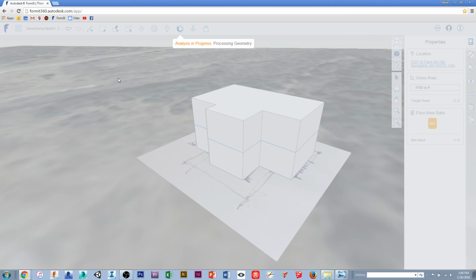And so as it's doing that, with this Insight analysis, we're going to see sort of this interface that I don't want to compare it to Pinterest because that's kind of silly, but that's kind of the notion. We've got all these little different boxes pinned into place on my Insight 360 that's built for this massing model. And each little window or each pin has specific data on it that's going to give me the opportunity to modify that data, like the type of HVAC system, how much glazing is on each surface, and immediately see the impact that that's going to have on my design thinking, or actually not just on the design thinking, but on the building performance itself.